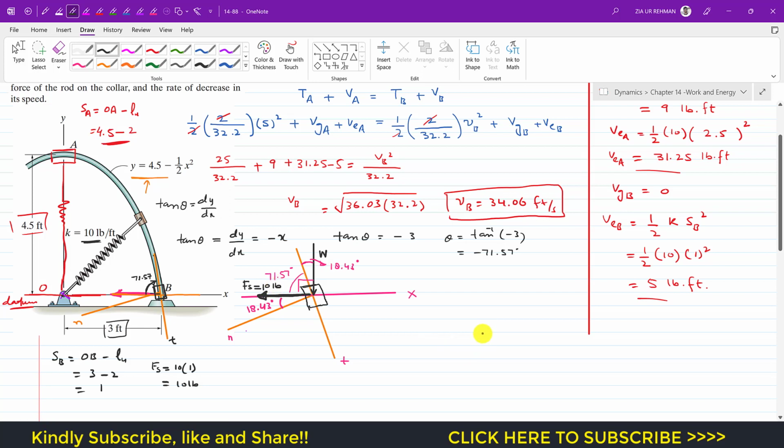Now if we want to find the normal force of the rod, the normal force of the rod is going to act in the negative n direction, like this. This is the normal force which is applied by the rod on the collar. And similarly, if I extend this normal axis, we can resolve this weight into its components. So the weight will have two components. One component of the weight is going to act in this direction, that is in the positive t direction. This one will be the cos component. And similarly, the other component of the weight is going to act in this direction, so we can place it here. This one will be the sine component.